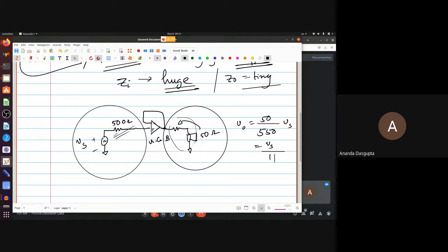As a result, whatever your signal is, almost the entire thing is the input. And because VO equals VI, the output is almost exactly that. And now that output gets fed across the speaker. And the issue is the output from the op amp, which has a very low output impedance.